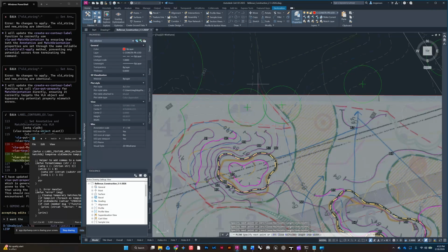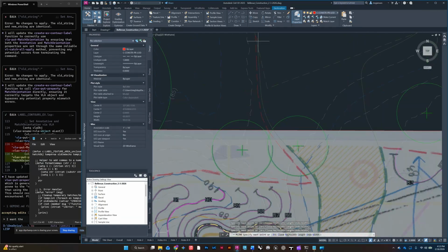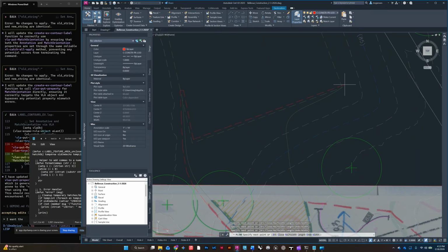For ones like this, I'm not even going to spline this edge. I'm just going to bring it in like this. I might spline this next edge, so I'm going to end this command, turn my snaps back on, snap, turn snaps off, so that I can come in and spline it.